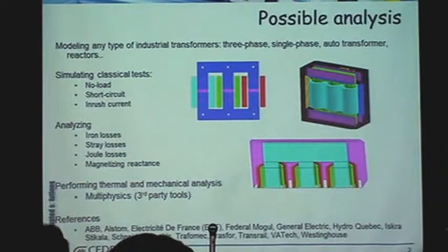So as far as Flux is concerned, if we were doing a thermal, we would probably stop just on the surface of all the components and just put convection or radiation coefficients to set the losses. Other tools are much better, Fluent, Star CCM, and others like this. So that's why we would go through third-party multi-physics tools.